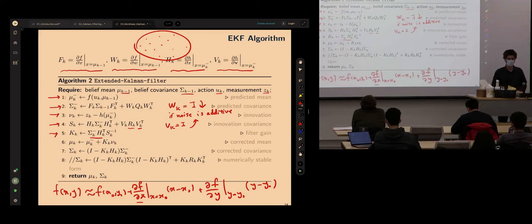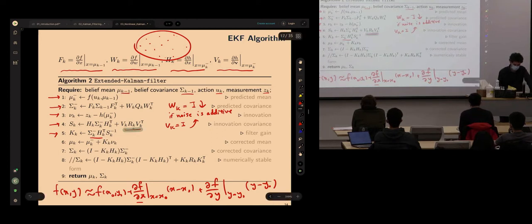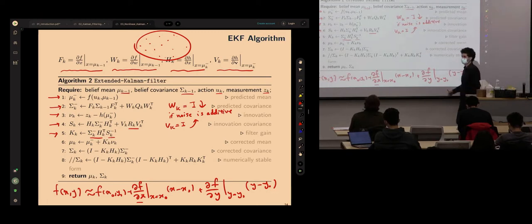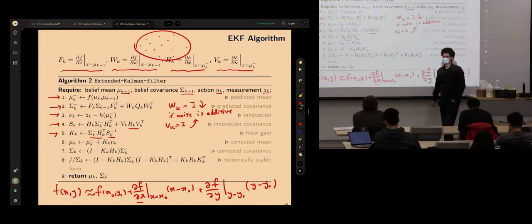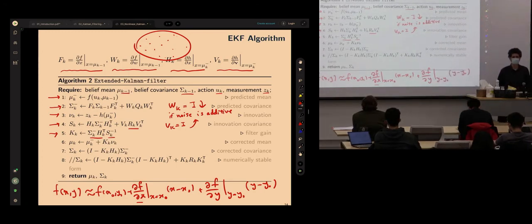Large covariance, small inverse, right? Small amount of information entering the filter. So this term will be small. Sorry, this term will be big, S inverse will be small, right? Is that correct? So big noise, small innovation information. Small innovation information, small filter gain.